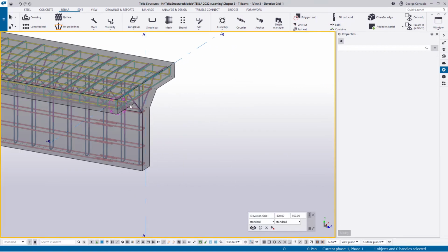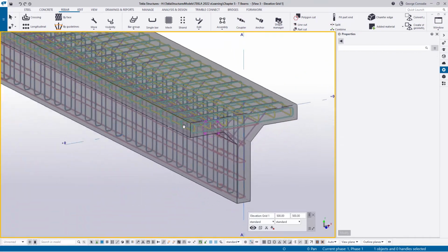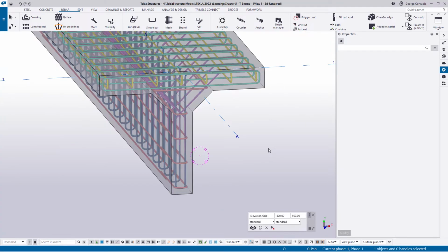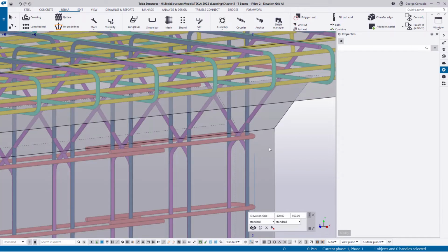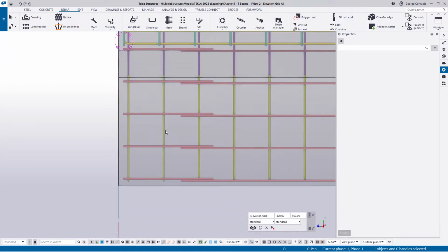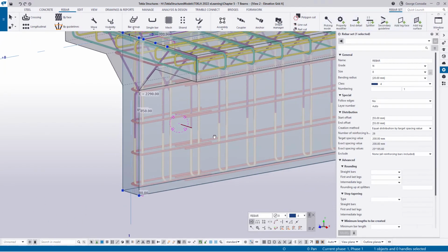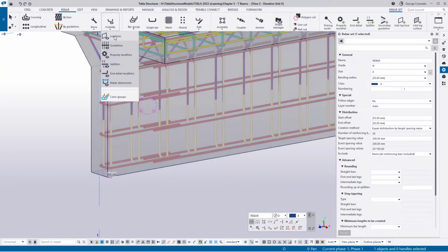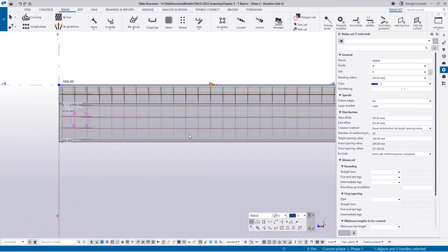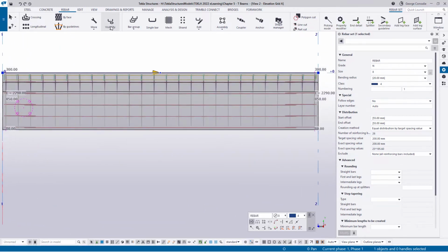So now that we've got all the bars in, this is all the bars we require, we can now start looking at spacing. Now, I think for this exercise, I'll go to the side elevation, Control P, side elevation, and let's pick these top hats, these long blue bars. Let me just make sure I've selected that long one. Let's pick that, and I'll switch off the leg visibility. Let's pick these bars as our main spacer, vertical spacer. And what we can do with them to start out with is, for this, I'm going to switch off all the modifiers because we don't need them anymore.